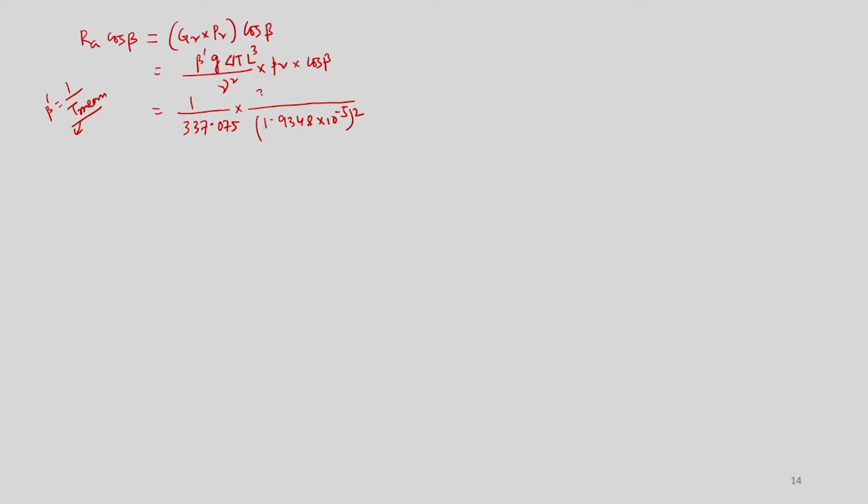Then we have delta T, 346.15 minus 328, and length is given as, length means the distance between these two plates. So, this is 0.05, this is a characteristic length. And we have Prandtl number 0.7192, right.